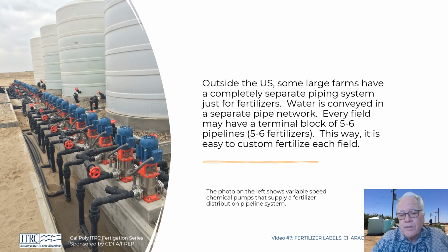And they may pressurize it, or these pumps can provide enough pressure so they don't even have to pressurize the fertilizer. Basically what they're doing is injecting it at the appropriate rate. In other words, they don't have tanks out in the field. They have outlets, kind of like turnouts at each field, for water and for each of the types of fertilizers that they have. And again, this is not common in the United States yet.